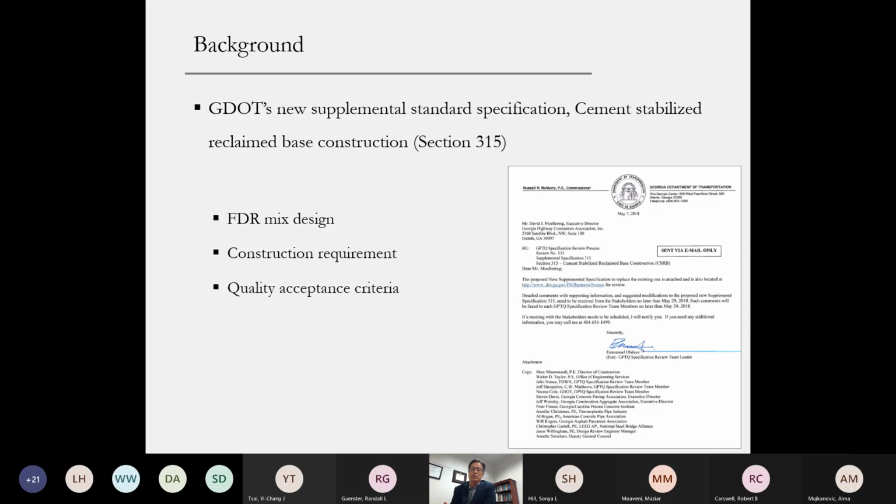But when you look at existing pavement sections, in general, most of them are not uniform, meaning that the thickness will vary by location. Subgrade strengths generally vary significantly, and therefore the base course thickness and density are going to vary significantly.